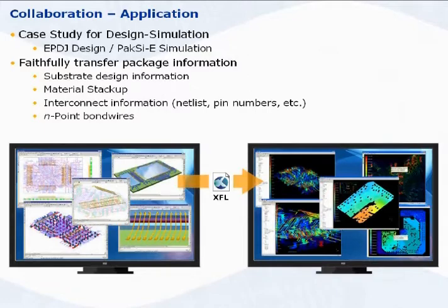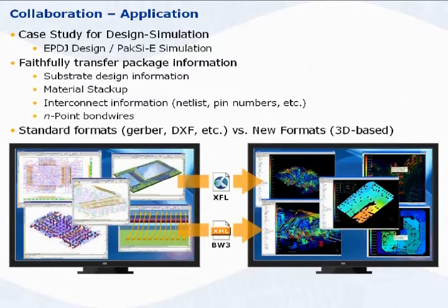For example, not limited to simple models. The idea is to transfer the data such that the simulation system can read the data and immediately be ready to simulate. There is no extra setup to rebuild geometry, define bond wires, solder balls, ports, etc. There is also a desire to avoid using formats that, although standardized, can only carry dumb information, and instead use intelligent formats that fully support 3D and all electrical information.